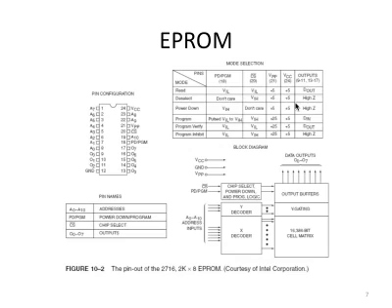So what you expect to see is this chip, if you look at its physical shape, it has to have 8 pins for data, because that's the data width. So you will expect to see, out of the pins coming out of the chip, at least 8 of them used for data connections. For the 2K, that's the size, the number of locations in this chip.